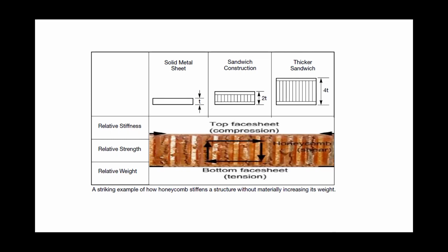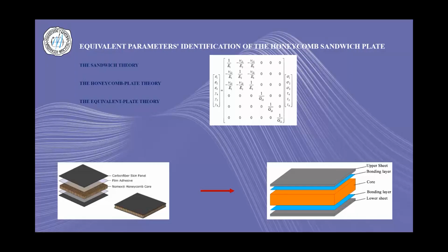However, just basically how the composite plate with the core takes the load: generally, the face sheets on the top and on the bottom are responsible for carrying the direct, actually the normal stresses, where the core mainly carries the shear stress. This will be very important at a later stage.